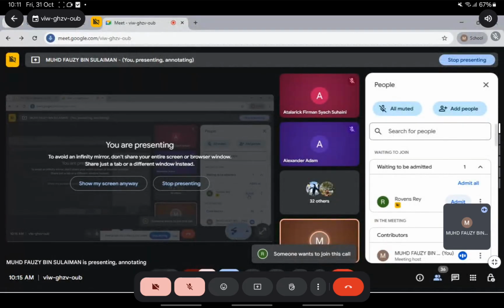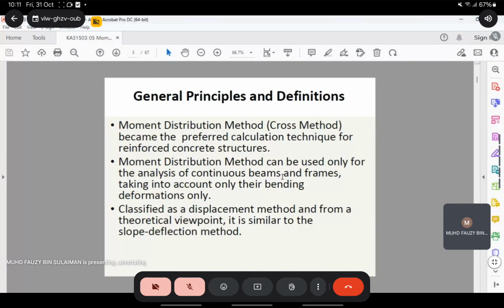In steel, we can design it for fixed support, but it's hard to construct, because you have to hang the steel beam before you weld it. If you are using bolt and nut, your structure is designed to be pin. So in order to fix a steel structure, you have to use welding connection.